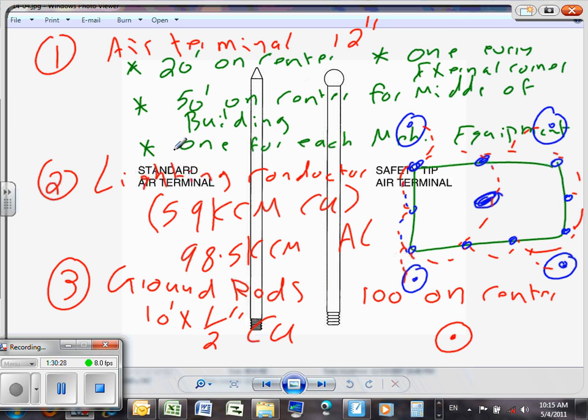Am I missing anything? And of course, guys, like our speaker said, with lightning you have to tie everything mechanical there. There's a ladder, I believe, that's sitting there. So you just grab, annotate a detailed line and tie it to the ladder. That's as far as we can go in terms of lightning design. All the detail drawings are going to be dumped into a drafting view and put in a sheet.